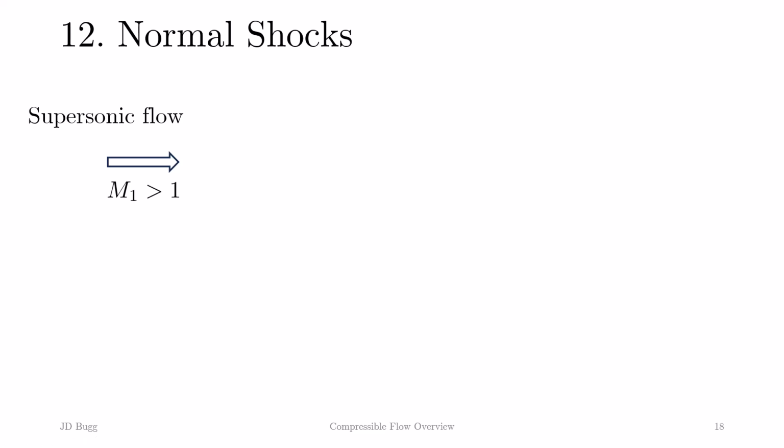However, if the downstream pressure is not low enough to sustain supersonic flow, a normal shock is going to occur in the duct. It's called a normal shock because it is perpendicular to the flow direction. We have a one-dimensional flow here from left to right. The flow upstream of the normal shock is always supersonic. The converging diverging nozzle we've considered so far will never have a normal shock in the converging section. The flow downstream of a normal shock is always subsonic.